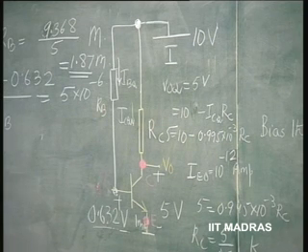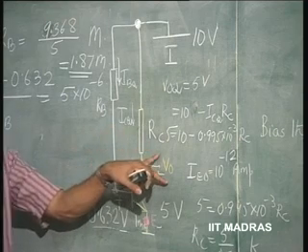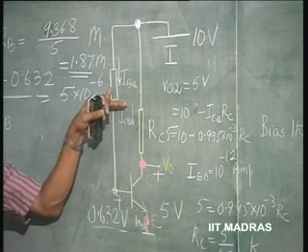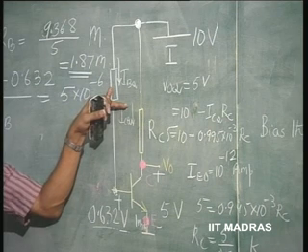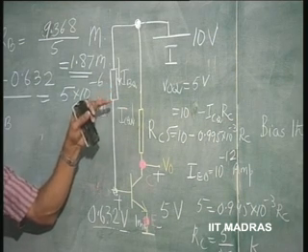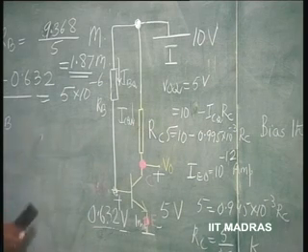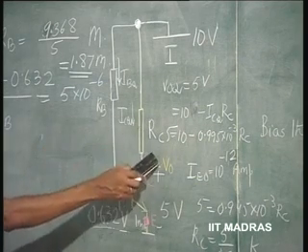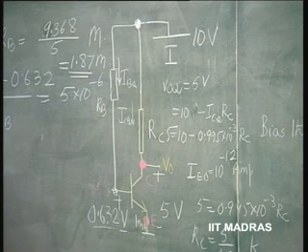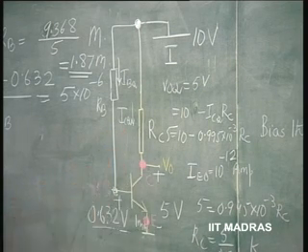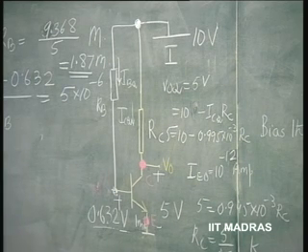So, this is a single supply biasing of the transistor in common emitter mode. It has to use two resistances, one to fix up the reverse bias voltage, RC, and another to fix up the forward bias current as IB. So, you can therefore bias a transistor like this by using RB and RC in common emitter mode. Emitter is a common terminal between the output and the input. But this also is not a very stable way of biasing.